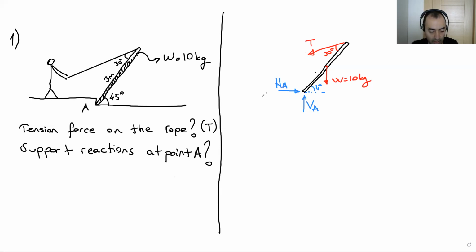And if this system is in balanced position, how do we define the equilibrium or balanced position? You can remember, we have three equations. What are they? Let's write them. You have to know this. This is really basic. Total X is 0, total Y 0, and total moment in any point is 0. This is the equilibrium definition, right? You know this.